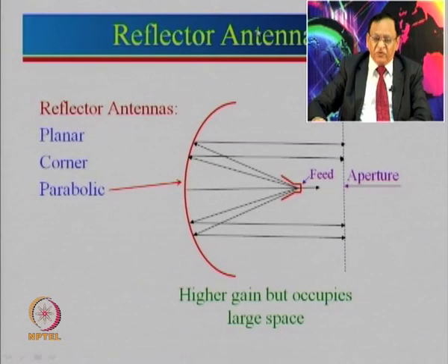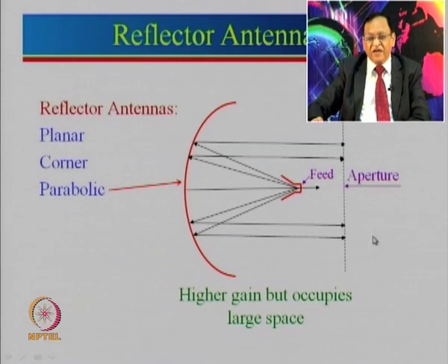People were using parabolic dish antennas for 25 dB or even 30 dB. We have redesigned these reflector antennas and realized a microstrip antenna which is flat, lightweight, occupies less volume and so on. When we discuss reflector antennas, we will also tell you what we did.